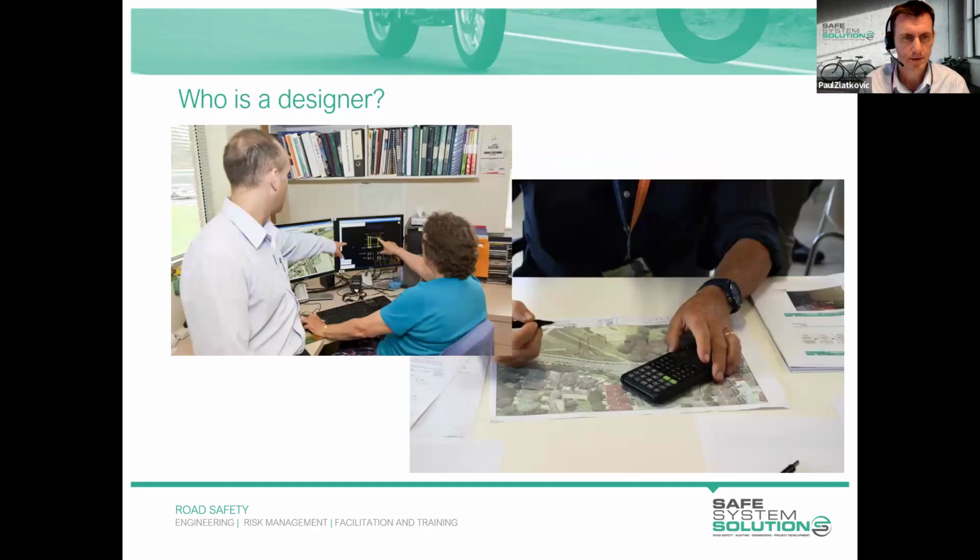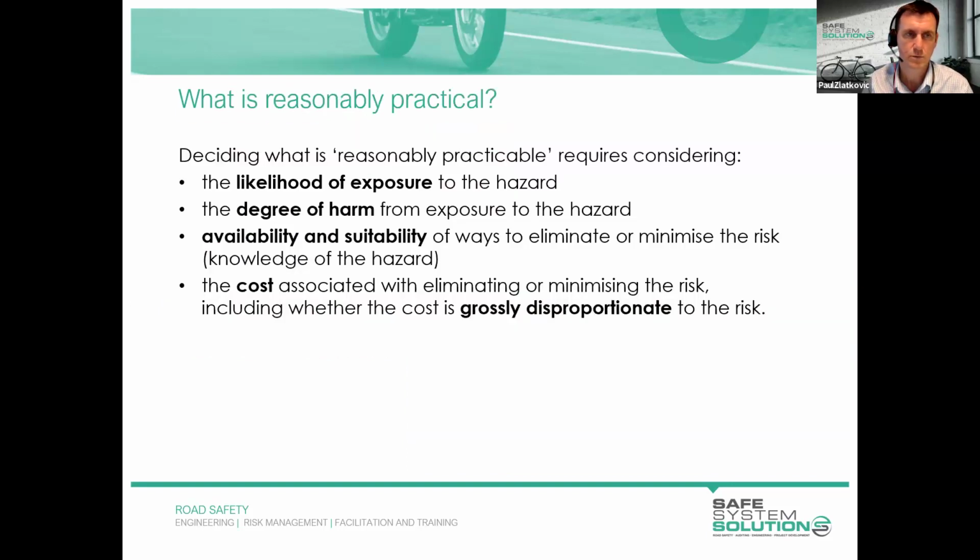Who is a designer? Not just those people in the pictures, but anyone who prepares sketches, plans, or drawings, or makes decisions that affect the structure is a designer. And we talked about what is reasonably practical, which requires consideration of all those things there: the likelihood of exposure to a hazard, the degree of harm coming from exposure to the hazard, ways that you can eliminate or minimise the risk, and the cost associated with it, and whether it's grossly disproportionate to the risk.